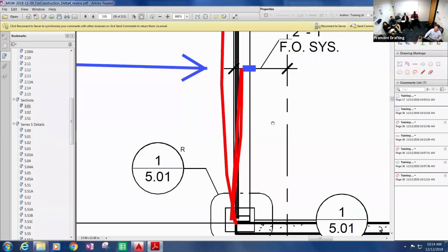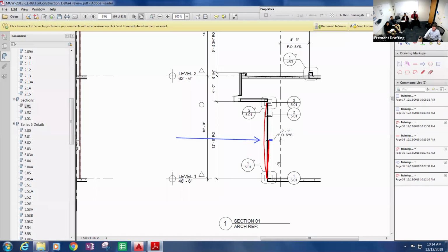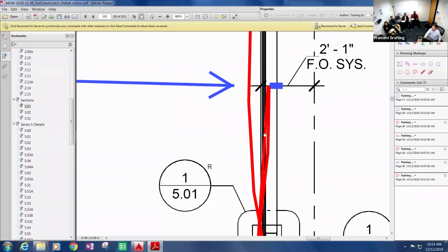Right, exactly. So I'm not measuring the glass deflection from what was the vertical piece of glass to this point. The glass itself, the head of the glass, has already come back in. And then I'm measuring from that theoretical straight line from the top to bottom, this kind of angle, for the deflection. That doesn't come up too often, but that's how we look at that.